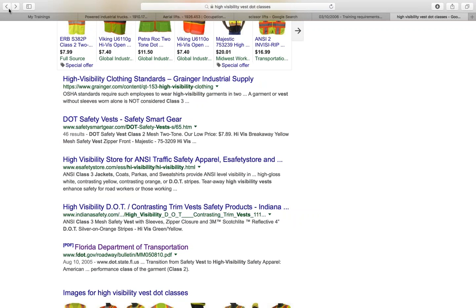Let's talk a little bit about soil contamination, and I'm at page 6, the top left of page 6. When working at a new construction site, right, performing a demolition, one thing we're going to have to make sure of is that there are no biological or chemical contaminants, right? Because we may be digging up old septic tanks, sewer tanks, contaminated land sites. It could be hazardous chemicals, or it could be biological hazards. Okay, so we have to make sure that we put warning signs up, right?